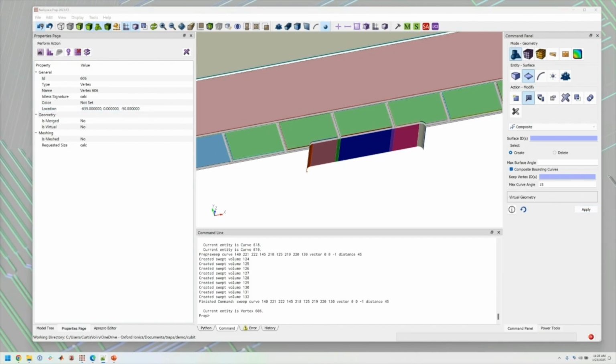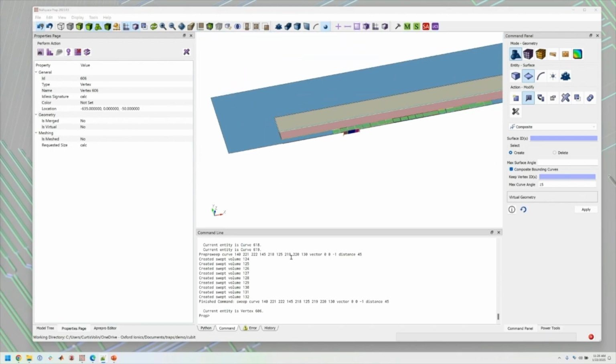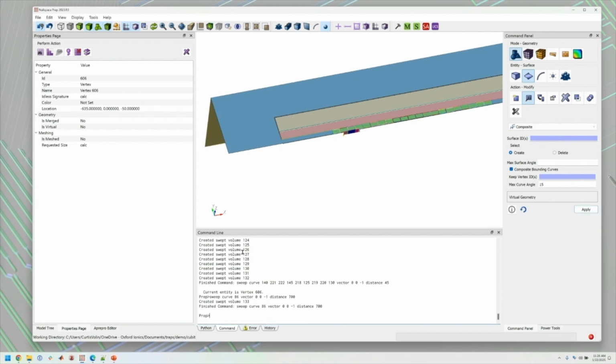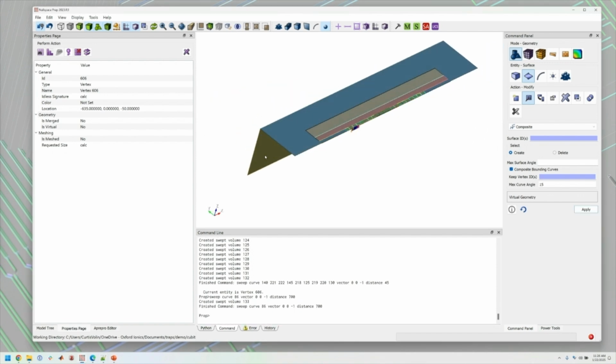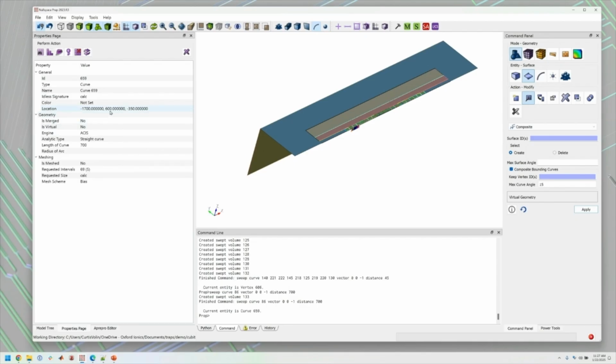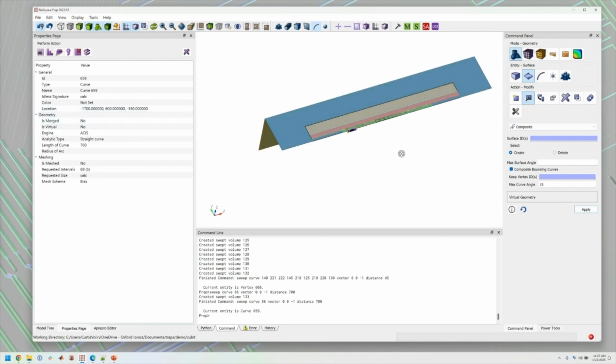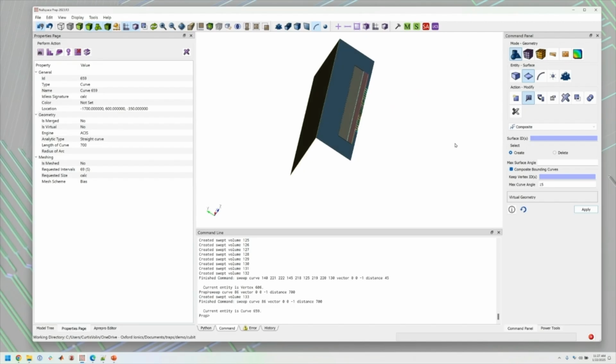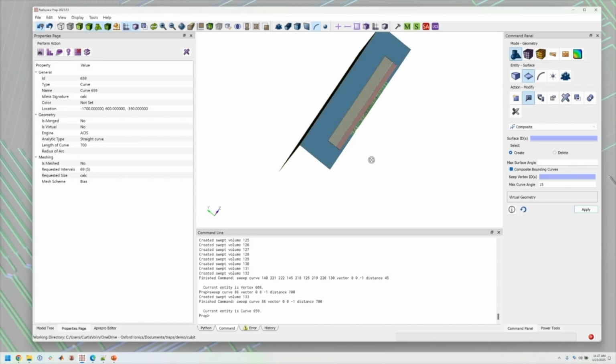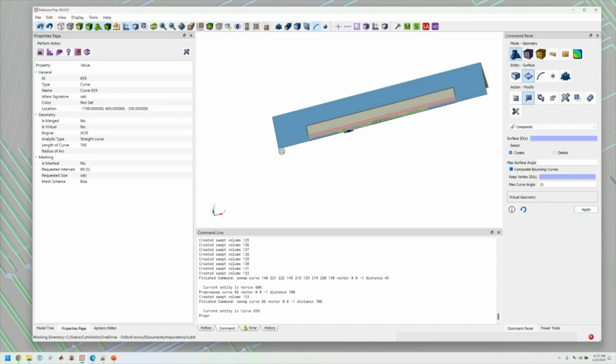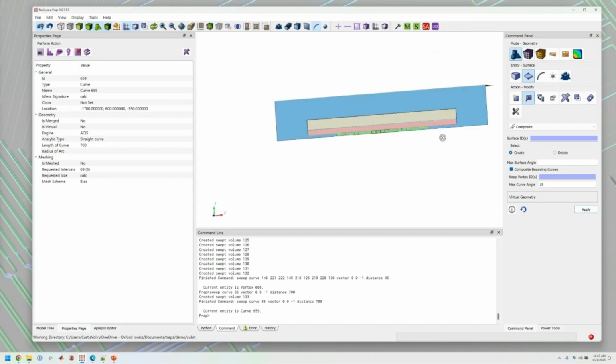And then the last thing I want to do is sweep the sidewall of the die. So I'm going to take this curve out here and sweep it down to the thickness of the silicon substrate, which is something like 700 microns. In this case, 600 is all I did. And so now we're sort of emulating a chunk of an entire trap. And in fact, we could add the geometry out here at the ends, but it's not especially important to do that for the sake of this demonstration.